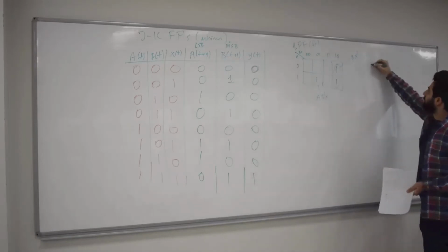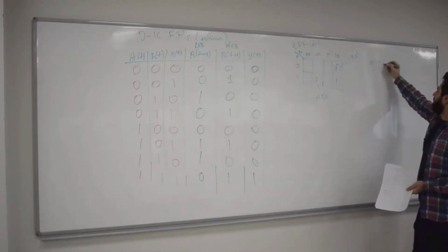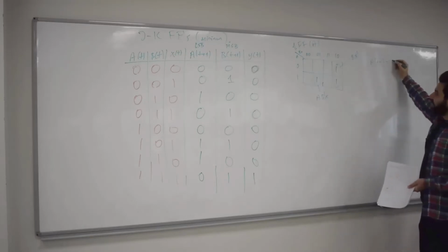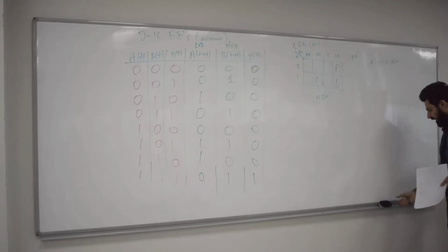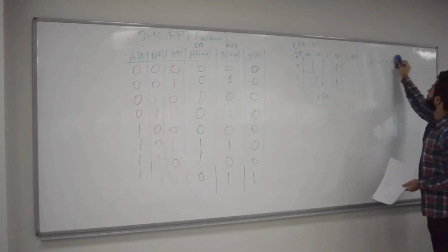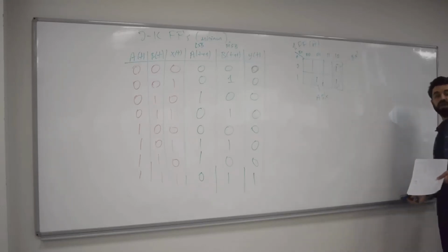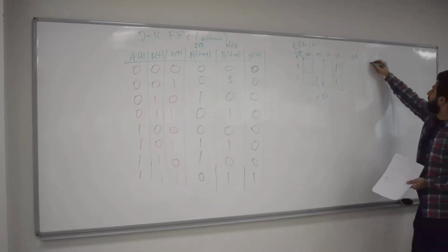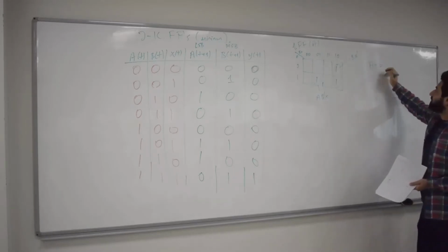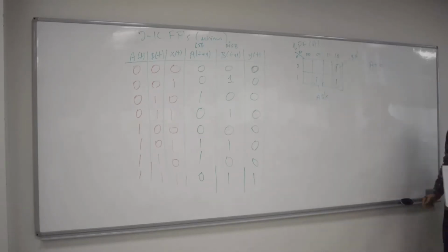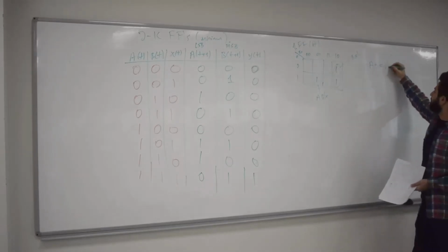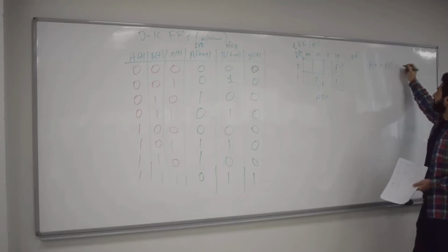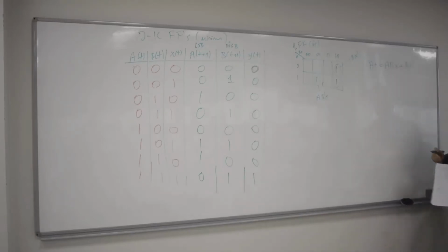Okay. So now I'm going to write A(t+1). A(t+1) equals A(t), because these are previous states. Or actually I can use, you know, the shorthand notation, which I actually mentioned last time. I use A plus to mean t plus 1, okay? So that's my next state. A plus equals A B prime X, plus B X prime, okay?